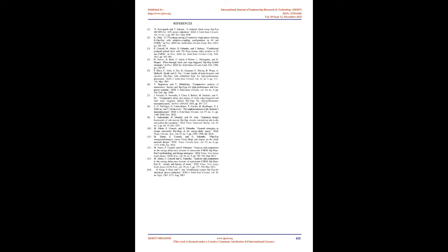When the clock is gated, the DPSCRFF has the lowest possible data input loading, a single transistor gate. The asymmetric propagation delay enables the use of highly skewed logic to reduce cycle time and energy. The glitching present at the output may cause additional energy dissipation in downstream logic, dependent on signal statistics.